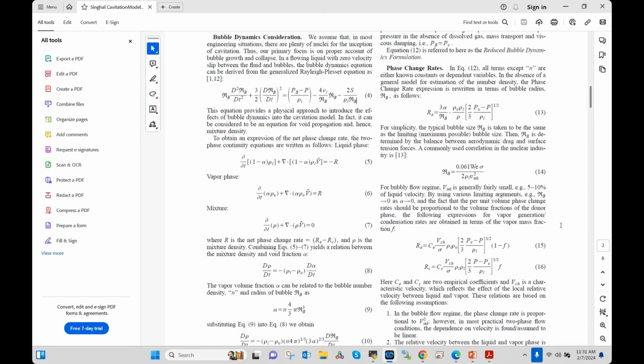From Sachin Kulkarni: for a coupled model, can we couple software like LS Dyna, which can give some complex motion to the mechanical boundaries? Yes, this can be done. All we need is basically how your surface is going to deform. We can take that spatial map, and then we can morph our geometry using our expressions to couple back and forth. So I think this is something that we have done in the past.